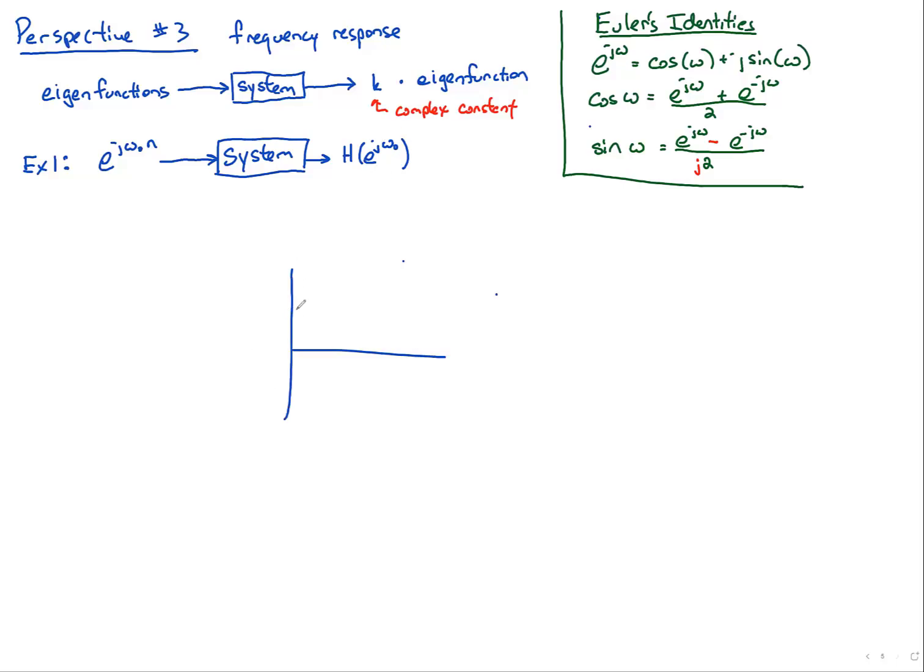We're not looking at something that's doing this with a real part and then something else for the imaginary part. This is a number. And this number is our complex coefficient that we had listed up here. And then we'll multiply this by our original e to the j omega naught n at that exact same frequency.